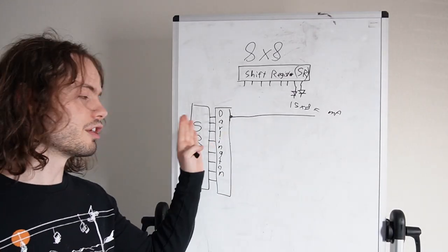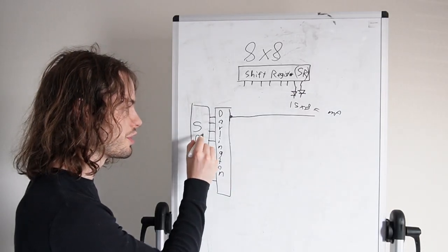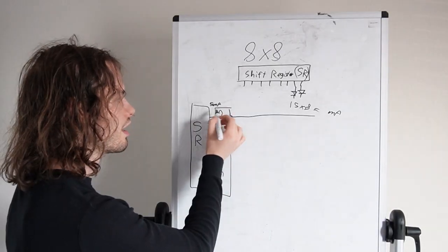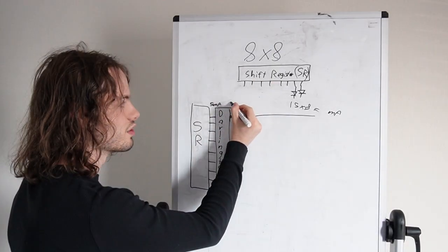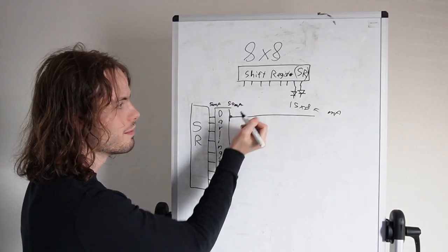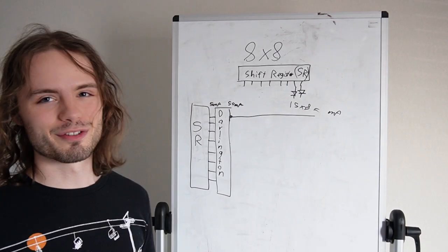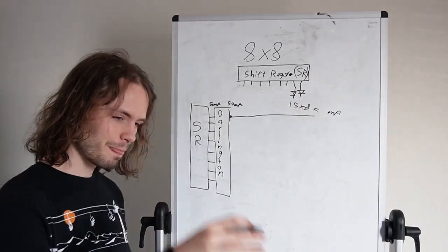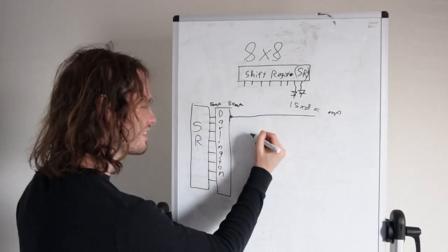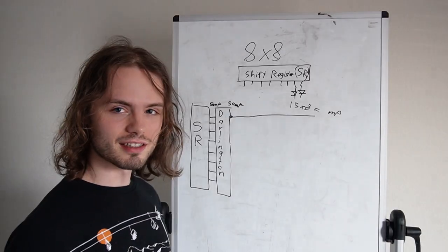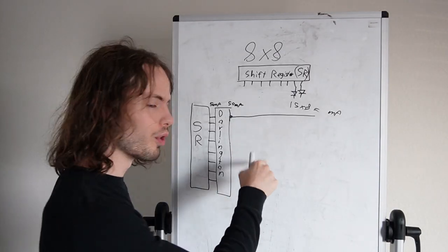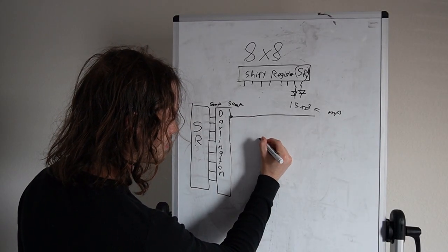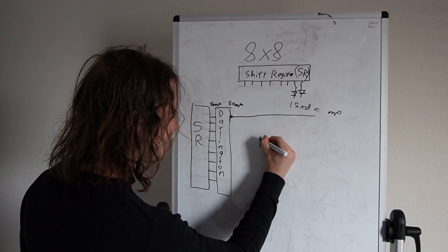that is why I use a Darlington, because this shift register can only supply around 5 milliamps per pin, and if I just 10x that, like I did with the BJT, it could carry maybe at max 50 milliamps, but 15 times 8 is greater than 50. I don't know the exact number, but I know it's greater than 50. So by using a Darlington, I'll go into a little bit of detail. A Darlington is basically 2 BJTs fed into one another, or one of them feeds into the base of the other. I know this with NPN, so I'm going to draw it like that.